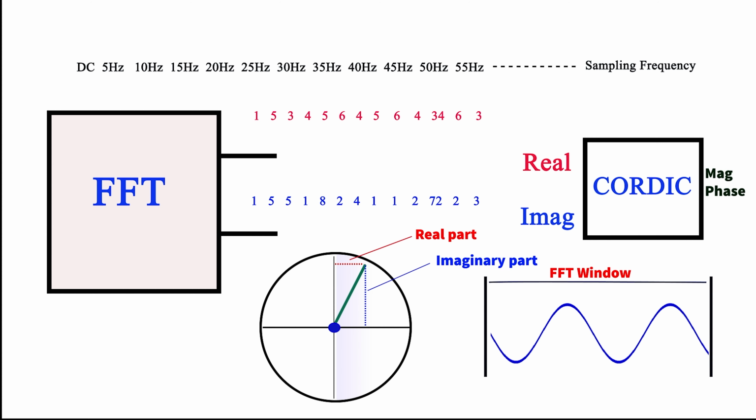So this is why, when we look at my system, I'm using two CORDIC blocks, one of them for the voltage channel and one of them for the current channel. And this is a really nice way to get the phase. Now, as an aside, we could actually find the phase of all the harmonic components if we wanted as well. And the hardware actually gives this to us. But I'm not sure how useful this would be, so I'll only export to the graphical user interface the phase of the voltage and the current.